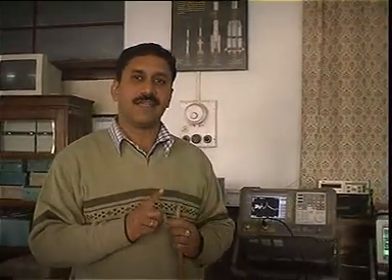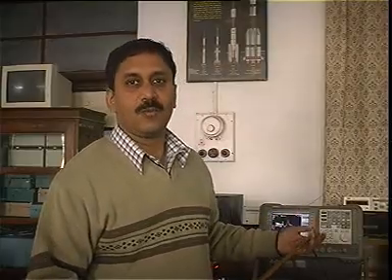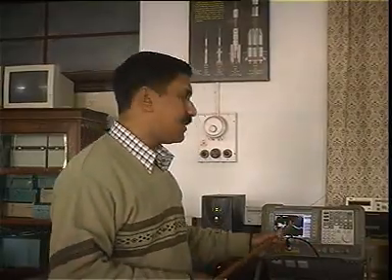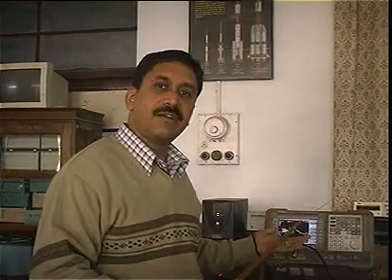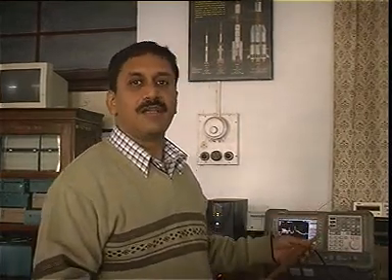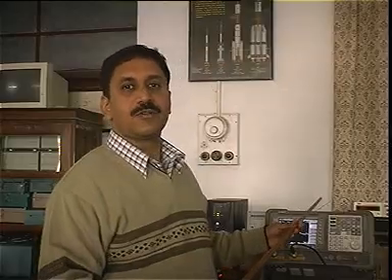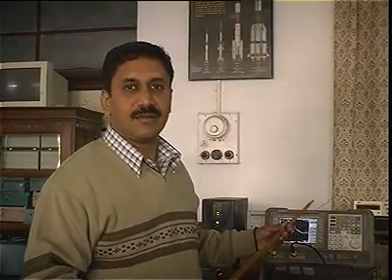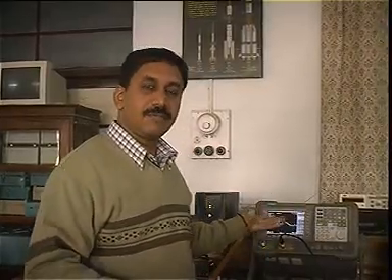So if I connect a BPSK signal to the spectrum analyzer, I'll expect only one peak, and that one peak will be located at 1 megahertz. Okay, I'm using a 1 megahertz carrier. Now, the phase information that is present in BPSK signal will be lost. Why? Because on this spectrum analyzer, I am measuring only the magnitude spectrum. I am not measuring the phase spectrum. To measure this phase spectrum, you will require what is called a vector analyzer, a network analyzer, which will give me both magnitude as well as phase. The phase information here is lost.